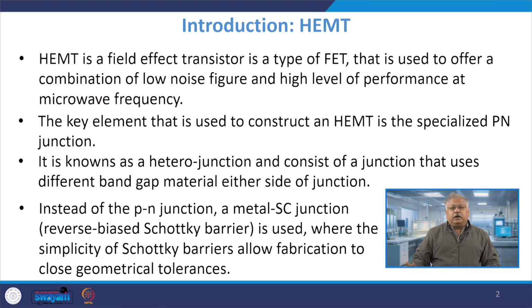As we already know, HEMT is a field effect transistor which is used to offer a combination of low noise figure and high level of performance at microwave frequency. Let me break it down into smaller pieces for your better understanding. The idea here is that, as the name suggests, it is a device which provides high electron mobility, right, because of certain phenomena, and when it does so, it provides a larger current as compared to its traditional counterpart of other FETs.